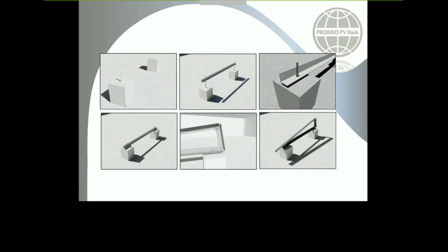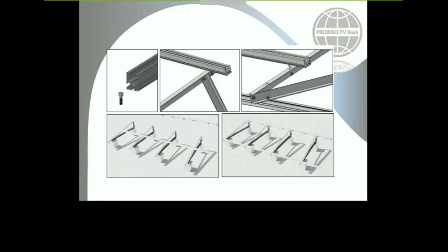Because sometimes you then try to fix the last profile and you can't, because you have already fixed the position of the profile. So it's always better to put everything in place, all the washers and the screws, and when you ensure that everything is correct, you tighten it. The next step is to put all the portal frames required, and once you have fixed everything, it is the moment to put the rails on.